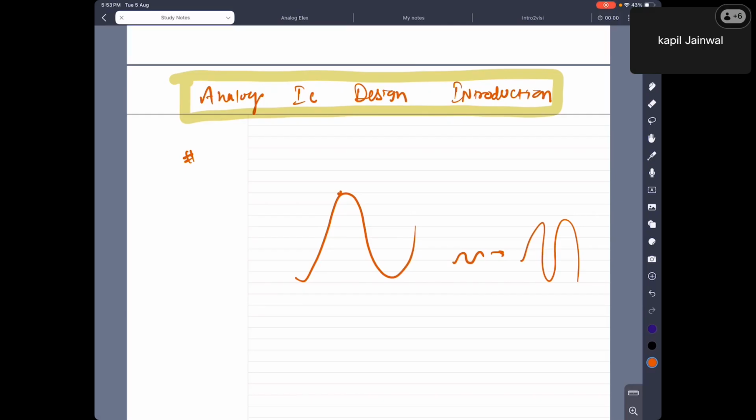These are the basic elements used to define a signal. So this overall property is called linearity. Not only linearity, but the noise performance, the transient performance, frequency analysis, signal range, power dissipation, the swing of the signal, all these things are very common and standard specifications for an analog system.